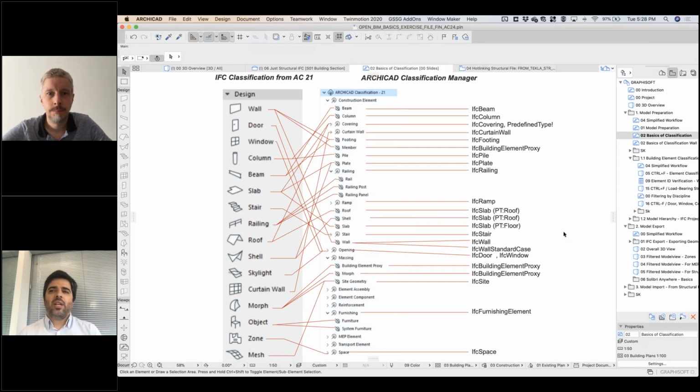For example, I can make furniture out of walls, or let's say a table: I have a tabletop with a slab, I have the legs with a slanted shape, and I use a column for that. Then I can select all those elements and classify the slab and the four legs done with columns as a furniture element, so that when I send that externally to, let's say, a structural engineer, he doesn't consider the columns from a table as structural columns.